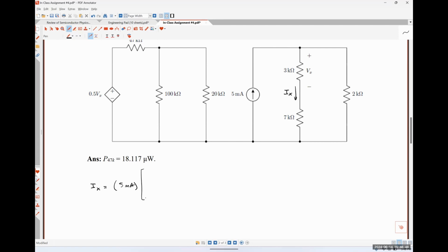So can we combine that and do 1/10? Absolutely. So ohms in the numerator. Ohms, okay. And then 1/10 ohms plus 1/2 ohms in the denominator. Absolutely. Kilo ohms. Yeah. And let's throw that into the calculator really quick. Actually, let's see. So that's 1/10 over 6/10. So 1/6 times 5 is 5/6 of a milliamp, if my mental math is correct.